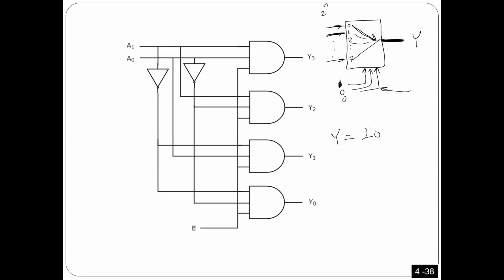Remember, I'm gonna tell you something important here. If you have an AND gate this way, for example, and you have here X prime, Y prime, Z prime, as I have just explained, when the input is minterm number 0, 0, 0, the output here is 1. That is the decoder, right? I'm gonna see how to do a little modification on this one to convert it from decoder to multiplexer.